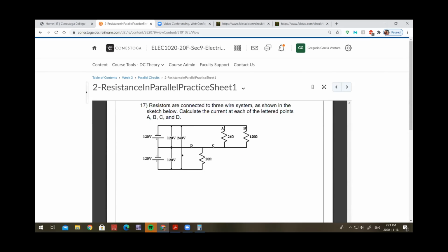In this instance, can you see that you have a negative terminal, and then the positive is connected to the negative. Remember what we were saying about additive polarity? Yeah, in series you'd add them together. Perfect. So this conductor here is going to be your neutral conductor. This one is going to be 120 between this point and this point.